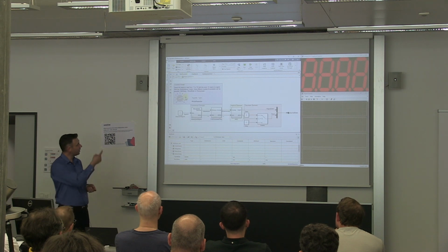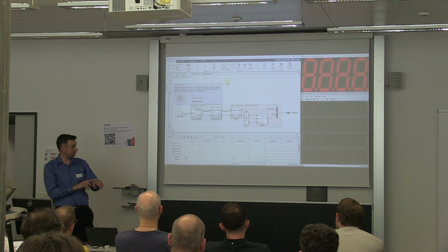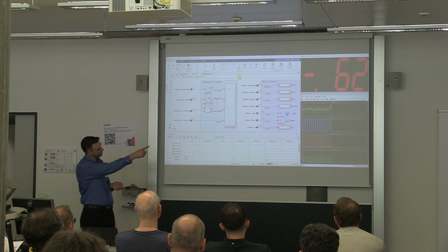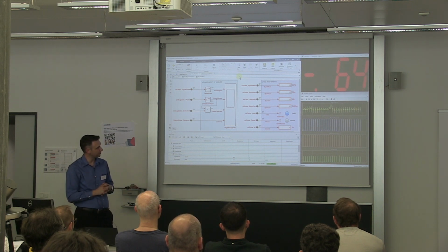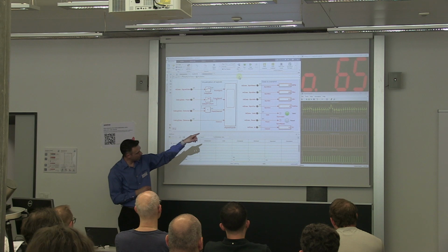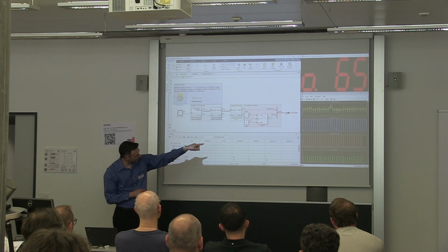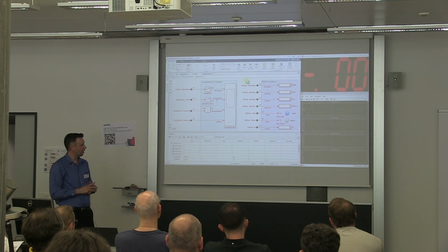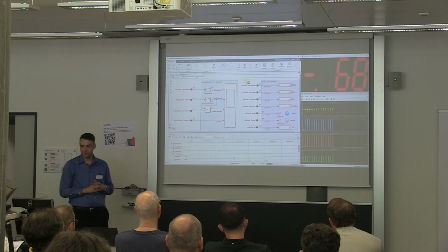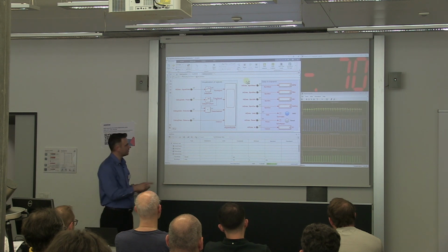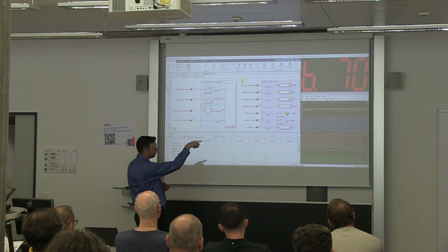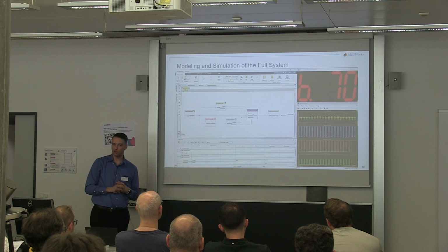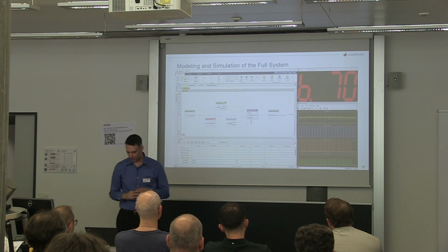Here in my case, I have my 10 signals that I collected from my smartwatch, and then I just run the simulation with the first signal. And then you can see how it looks. So the 7-segment display is updated, and then you have the raw signal in yellow, the pulse signal in blue, the peak signal in red, and then the distance between the high-frequency peaks. I'm just doing a second measurement, this time with another type of signal where there is an arrhythmia. And you will see that the encoding on the left-hand side is no more A or this round, but it's the symbol B now, in order to detect that this was not a normal sinusoidal rhythm, but an arrhythmia.